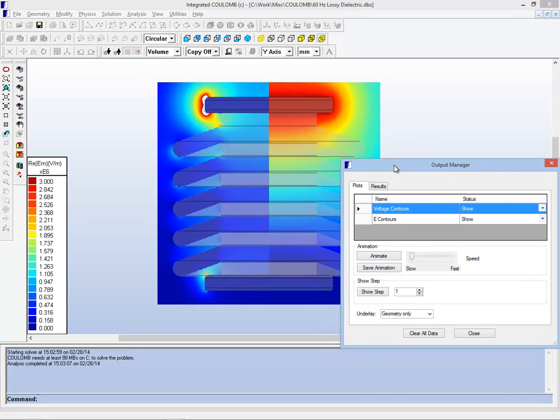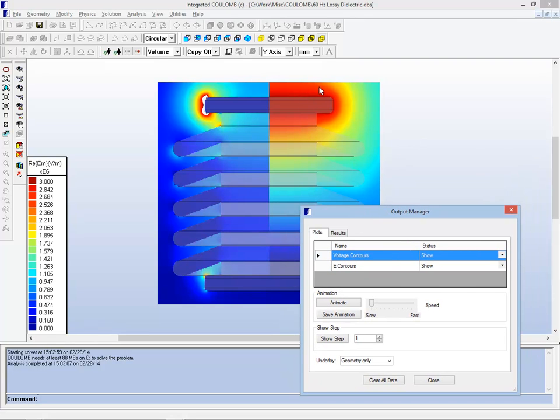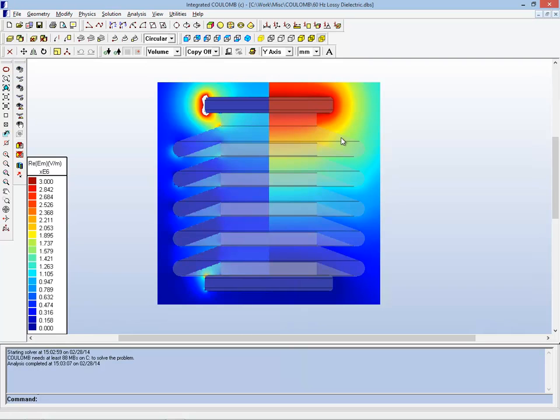The voltages go from the high applied voltage down towards ground, from the top cap to the bottom cap, and you will notice that the voltage dies off very quickly around the top cap. That's reflected in the field by the fact that the field is highest very close to the top cap. So for this situation where permittivity is dominating, the electric field is very high right by the top cap and very small as we go down the sheds.